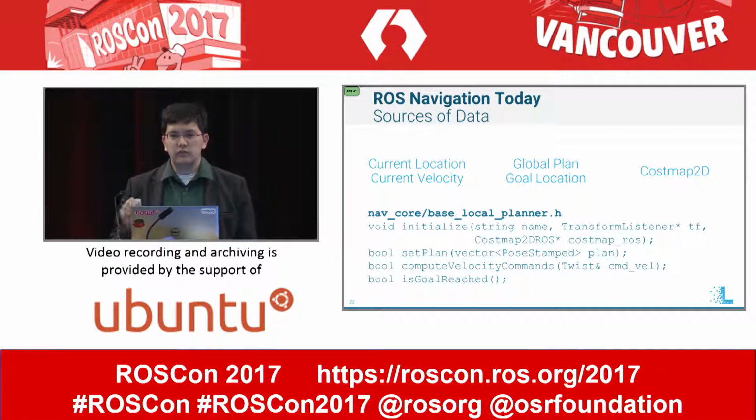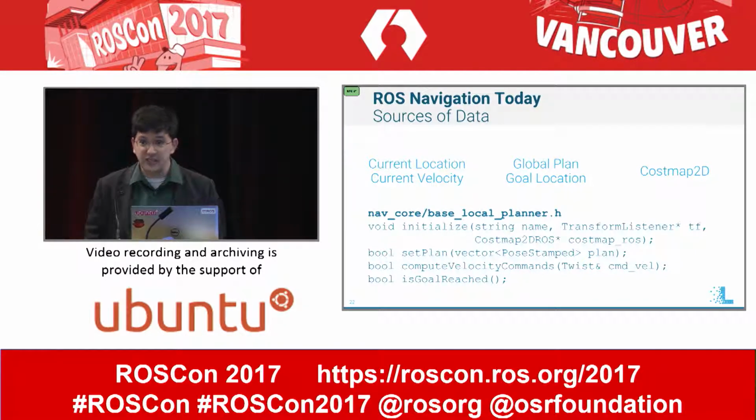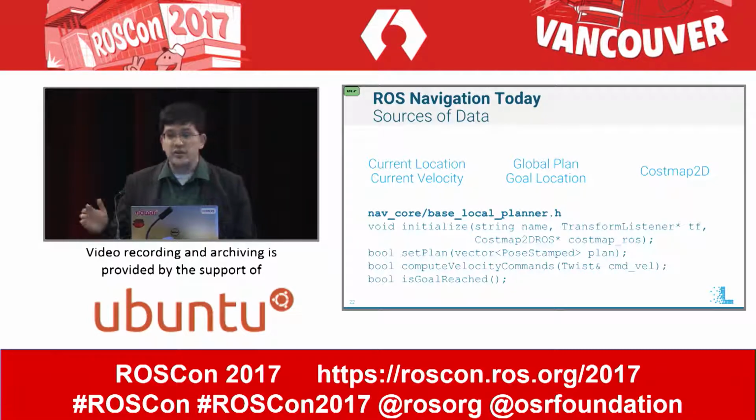So the current robot location is sort of implicitly in there in the transform listener, but in order to change that, you actually have to broadcast transforms, and that makes testing very difficult. And similarly, the current robot velocity is not in here at all. And so usually it's handled by subscribing to odometry underneath the surface, not through this interface. And so that makes local planners very difficult to test and also very difficult to customize.